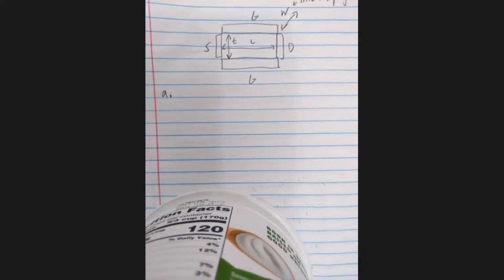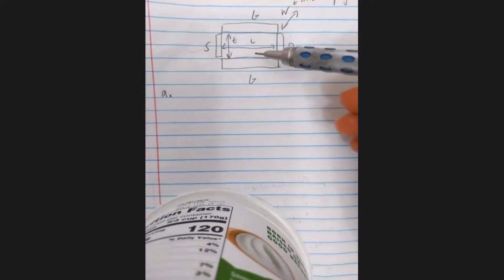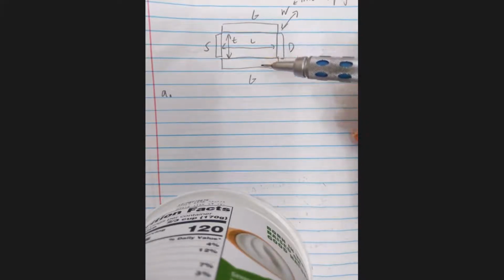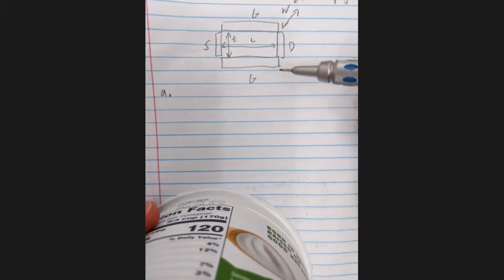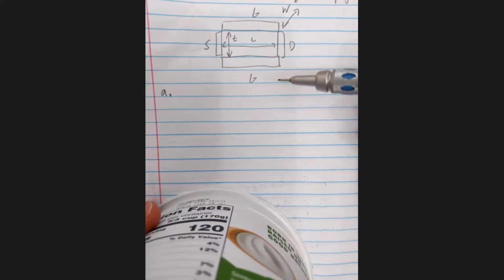Part A of this problem is more or less supposed to be a warm-up. Here we're asking, suppose the semiconductor bar in the middle of the structure is not actually p-type but is intrinsic silicon, then what would the resistance of the structure be? To do that, we need to find the resistivity, and we also need the dimensions. Luckily, I think all of the dimensions are given, so it's more or less plug and chug.